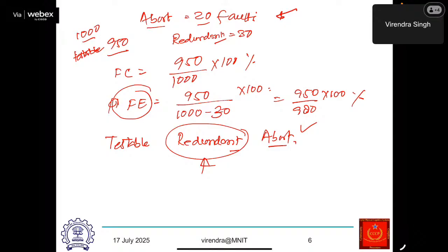So I may not be able to explore all possibilities, and in the worst case I may need to go through a path, because in some cases there is no test, and unless I exhaust all the possibilities, I may not be able to declare whether the fault is a redundant fault or not. Or maybe after exploring all possibilities, there may be only one test vector, and I get that after exploring all possibilities.